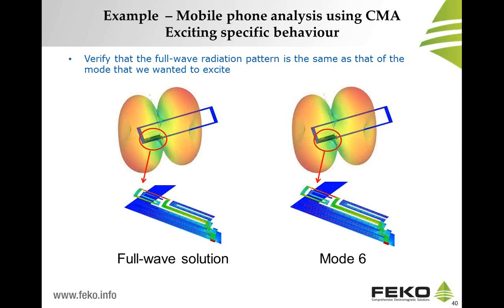And we can again check this by firstly calculating a full wave solution, that is just a plain method of moments analysis of our structure, and comparing this to our characteristic mode analysis that is associated with this particular mode that we would like to excite, and correlating with the graphs shown on the previous slide, we see that the behavior is very much the same. So modal weighting coefficients provide us with a way in which to optimize a certain mode behavior in order to closely resemble that of the full wave operating principle.